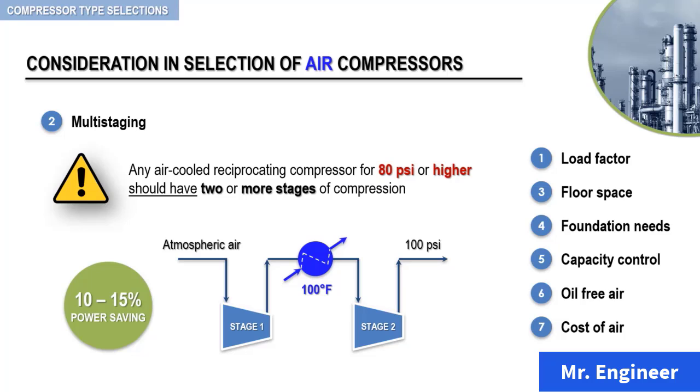Heavy-duty water-cooled units for the same service are more economical to operate than the air-cooled units and normally run at lower speed and temperature. Therefore, maintenance will consistently be less. For this reason, they are universally two-staged for 100 psi air service above 125 brake horsepower.